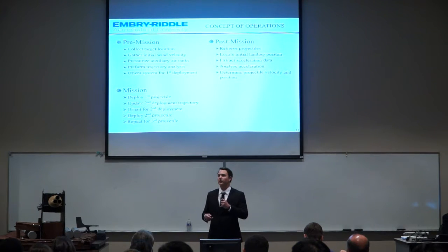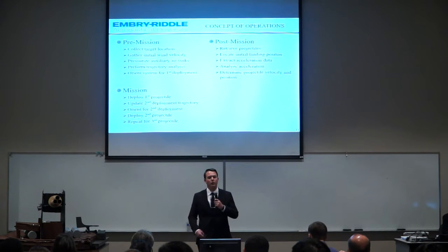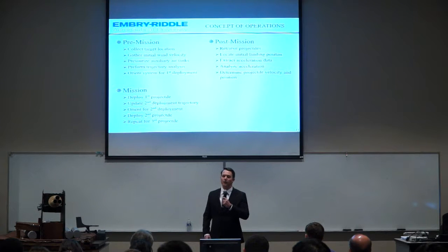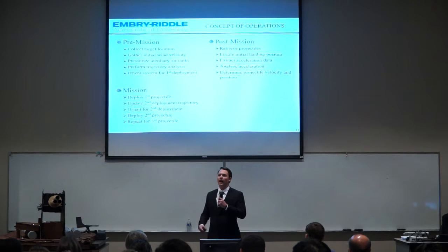Now, on the mission, again, which has a 1-minute time frame, which will begin with the deployment of the first projectile, we'll then update the second deployment trajectory, orient the system for the second projectile launch, deploy that second projectile, and repeat those steps for the third projectile. Now, in our post-mission, we'll retrieve our projectiles, locate their initial landing position, extract acceleration data, analyze that acceleration data, and determine projectile velocity and position during its flight.